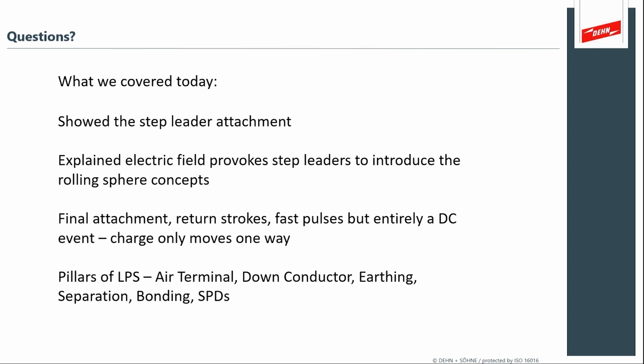But another thing is there are also typical preferred distances between the down conductors that the standard gives. So you can also look at the lightning protection system and see the number of down conductors, and that will also give you an idea of what lightning protection level it was designed according to. And then, like Mark said, the separation distance is also something that can guide you towards what lightning protection level the design was done according to. Mark, do you have anything to add?